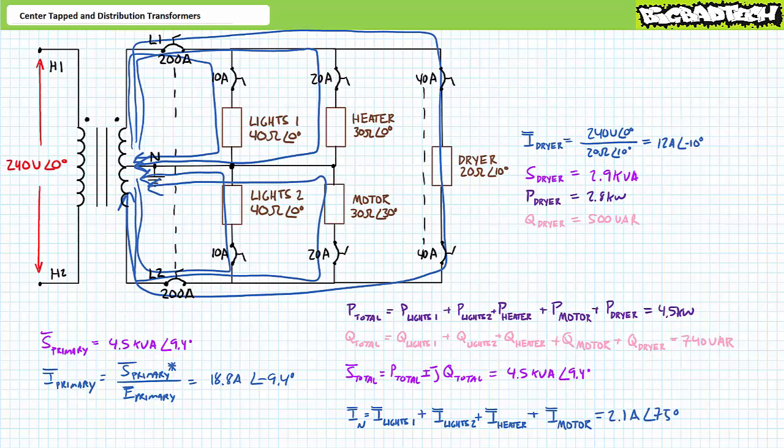You note the single-phase loads require the neutral line to function as intended. As these examples illustrated, any imbalance between L1 and L2 results in current traveling in the neutral line. Only in the very rare occasion with equal loads on the opposite phases does it result in no current traveling in the neutral line. This is one of the compelling reasons circuit breakers make or break connection with the hot or high side of the distribution transformer rather than the neutral line.